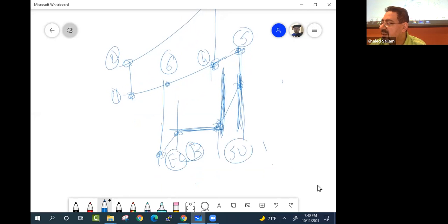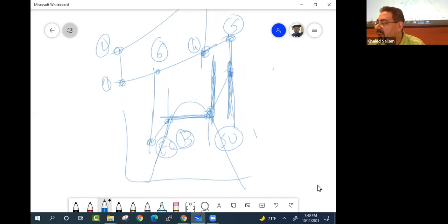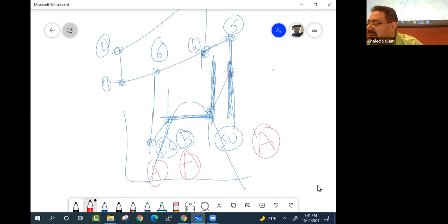And so what's really required from us is, this is the TS diagram of the water vapor. So we need the area here, the area here, the area here. So what does that tell us? I'm going to use the heat transfer equation, Q equals U A delta T, right? So I need my delta T. I need this temperature, this temperature, this temperature, and this temperature. What is that temperature? And over here, I need this temperature.